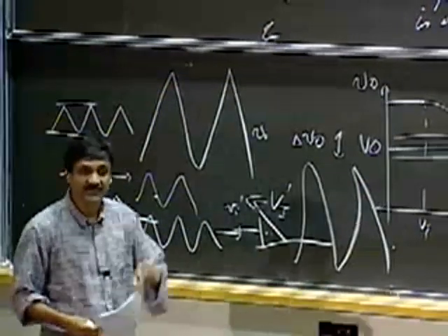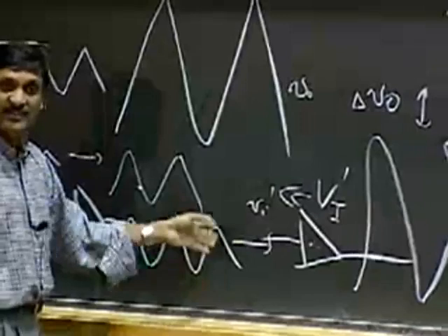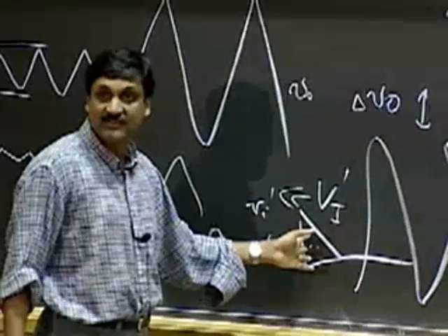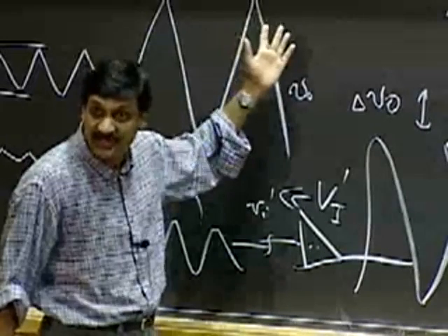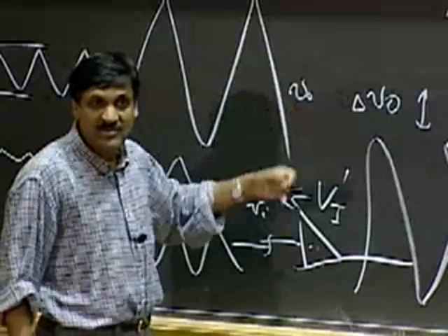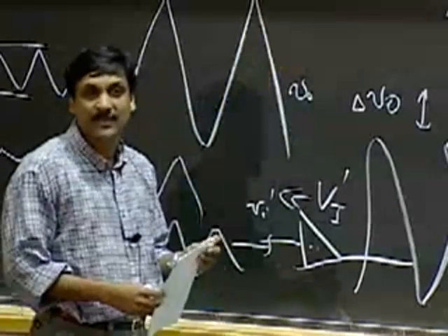It's a design question. You need to design it in a way that the signals of interest are much smaller than the bias voltage of this amplifier. So you may have to use much higher supply voltages. My amplifier, I believe, has a 4-volt or 5-volt supply. You may have to use an amplifier with a much bigger supply, different values of RL and so on.